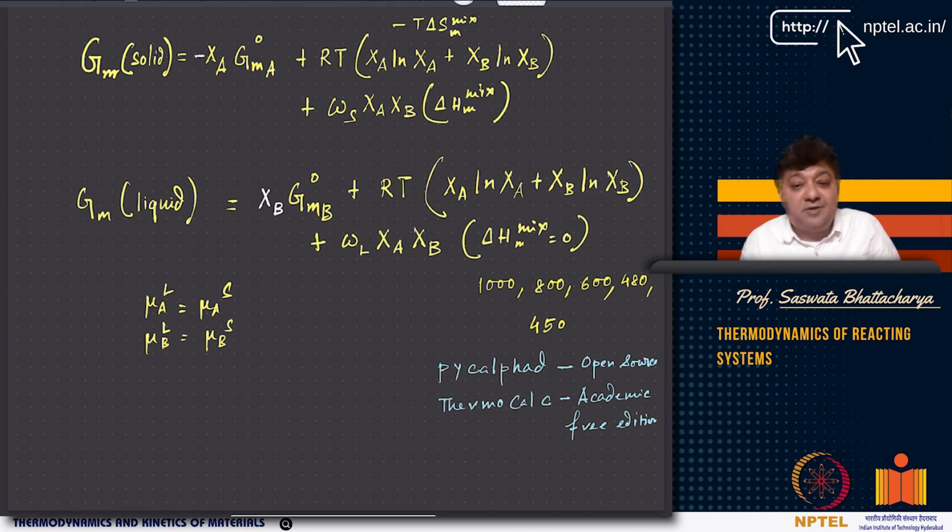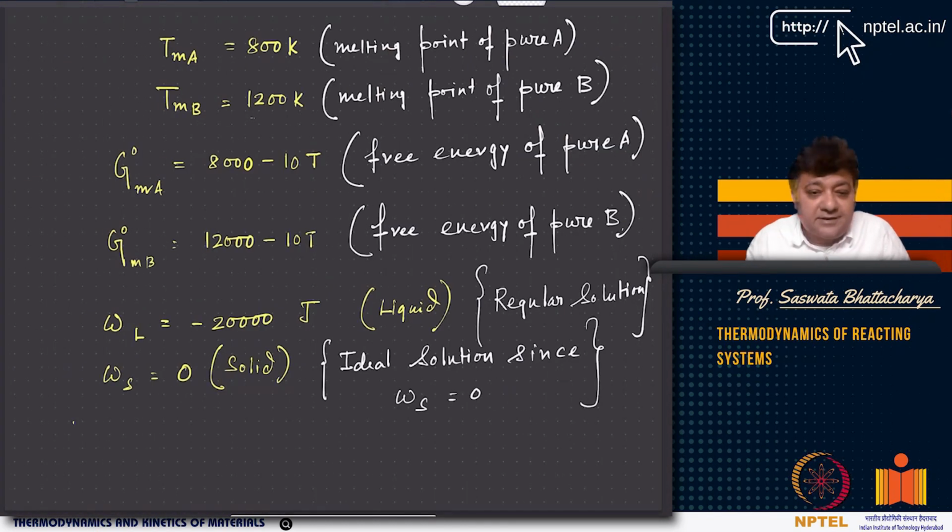You have more sophisticated models based on compound energy formalism, and basically it is given by a special polynomial called Redlich-Kister polynomial. So basically they are using such, right? Here we are using the regular solution model, but the idea is the same. The idea is simple. So once you have all this data, the pure elements data, the component data, and you have all the interaction data, everything.